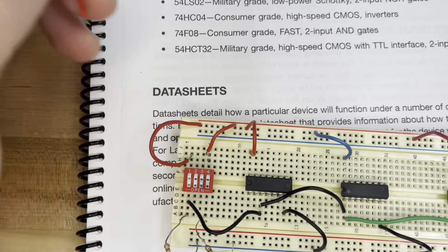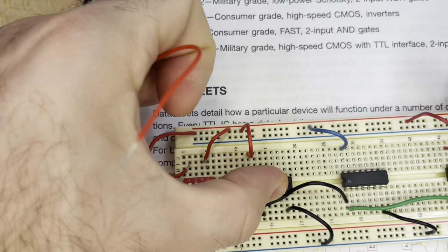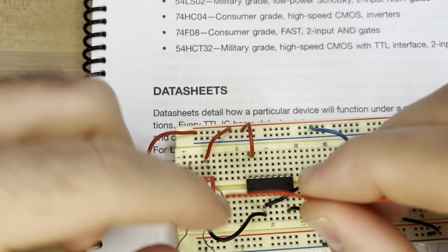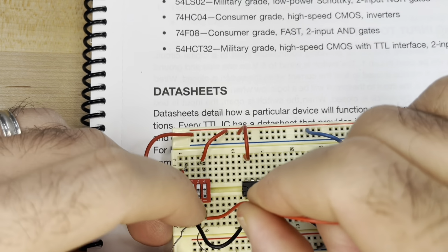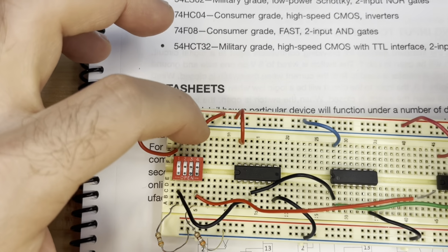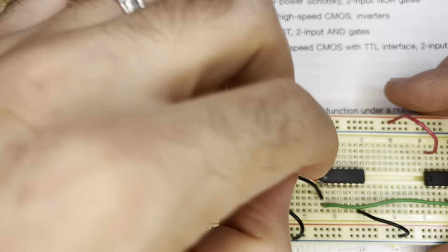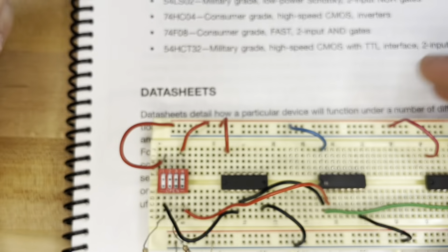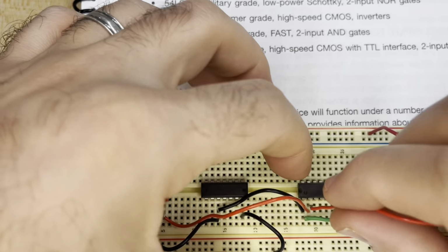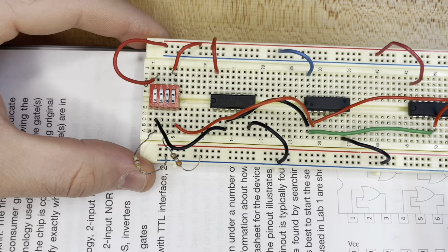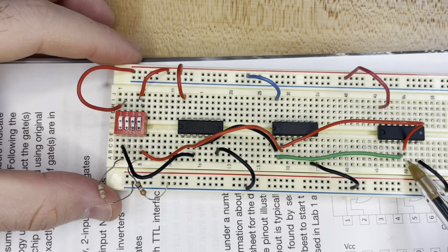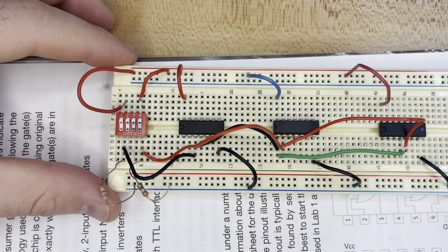So hence we know, like, Y is on DB switch number 4. We're gonna take from that point, and here we go. We're not gonna use Y naught, so we're gonna jump to the second IC, and then we're gonna use pin number 2, hence it's the second input. Same thing we do for Y. So we take it to pin number 5 on the OR gate. Now we have the circuit ready.